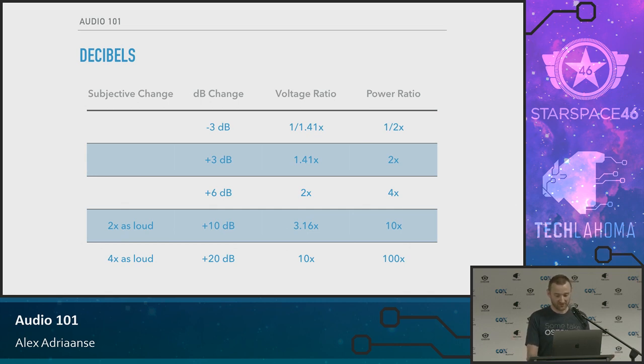The one other thing I forgot to mention is that decibels generally are relative. So when you say something is 85 decibels, that means nothing. Now, there are reference points. For example, you may have a reference point in voltage, called dBV. Or for sound pressure levels, a common reference point is something called A weighting or C weighting, and you'll see dBA, dBC. So 95 or 100 dBA, dBC is quite loud, but you always have to put that in the context of some type of reference point or some type of weighting.